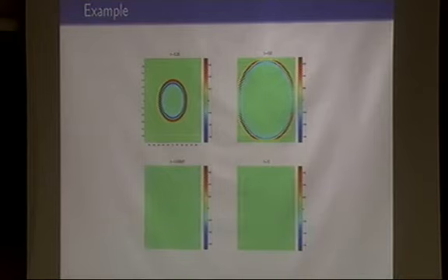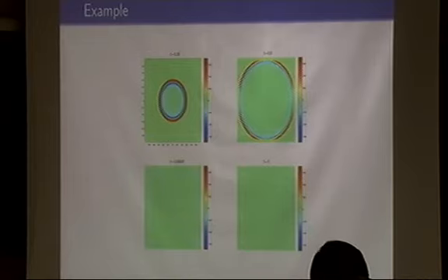If you have a high frequency, you have to have strong damping, or you have to have a larger bumper layer. Right. So it depends on the time. Depends, yes, exactly. For example, the wave propagates, and then you have to bump. So you can see that here you don't have any solutions. You don't need two bumps, right? The problem is if you have many sources in the domain, you don't know exactly when such waves reach the domain. So a priori we put these absorbing boundary layers in at the initial time already.